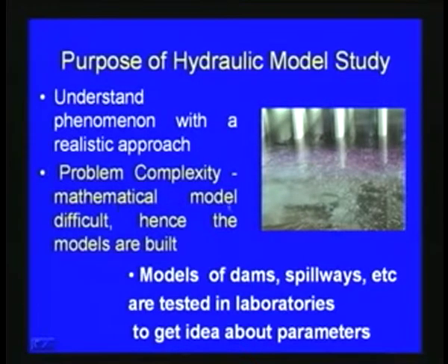The mathematical model is difficult, but if you do the modeling appropriately with respect to scale, we can see how the turbulence is generated, how much turbulence is generated, and whether the pumps are affected or the system is stable. So, in some cases wherever theory cannot directly solve the problem or mathematical modeling is difficult, then physical modeling or hydraulic model study helps.